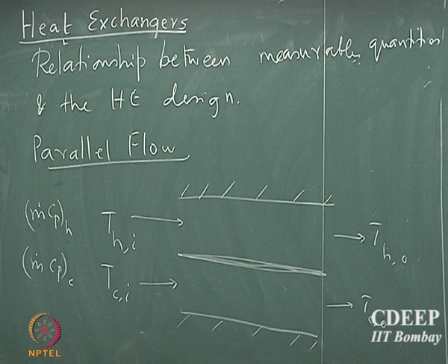Axial conduction is always there, except that there are some situations where you can say that the convection mode is dominating over the conduction. Some of these aspects you will actually see in your reaction engineering class later. Something called a Peclet number characterizes the time scale for dispersion and the time scale for convection. Depending upon the Peclet number, one could discern when axial conduction or axial thermal dispersion is important.